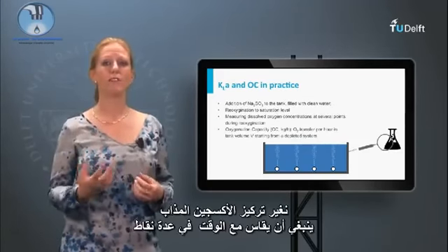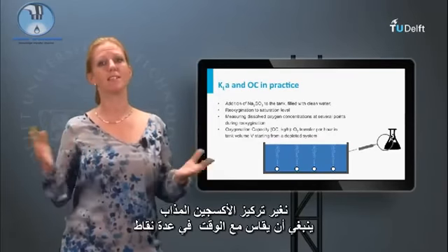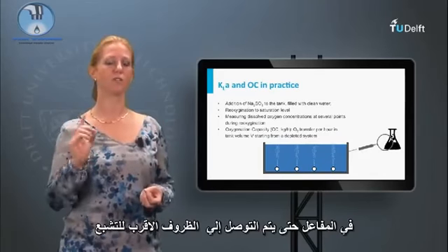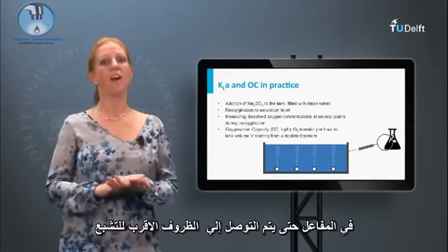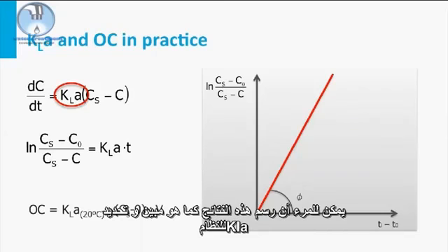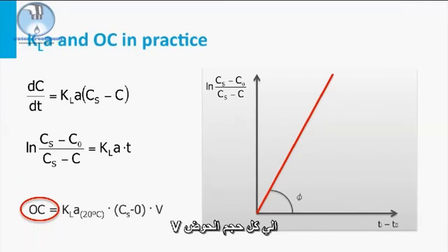The course of the dissolved oxygen concentration should be measured in time at several points in the reactor until near saturation conditions are reached. One can plot these findings as shown and find the KLA of the system. The oxygenation capacity of the aerator is the quantity of oxygen in kilos transferred in the total tank volume V.